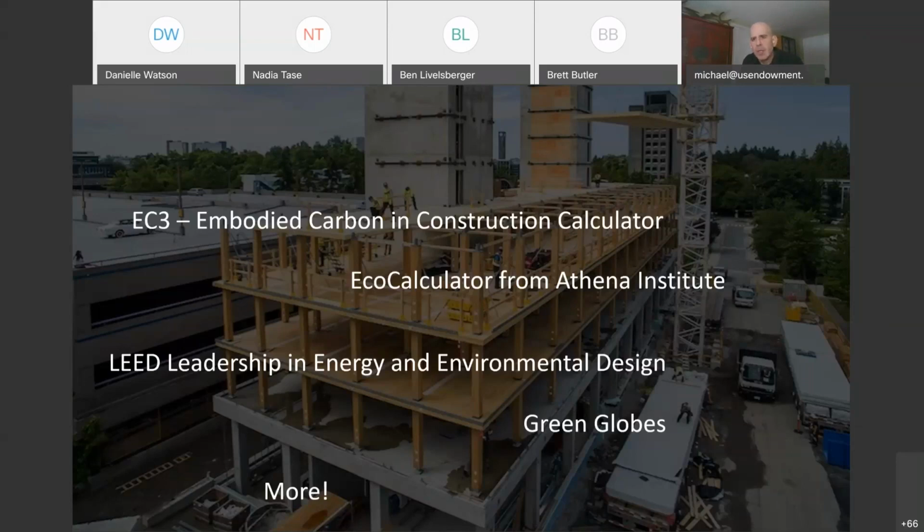It's sort of interesting: if you're looking for an environmental product declaration, an EPD, for concrete, you can go to a ready-mix facility. These are the concrete facilities that you spot all over the country that produce the concrete that goes into those trucks that have the rotating drums on them. They can produce an EPD at most of those facilities for any different type of mix of concrete because they just change a few calculations, they develop an EPD for that, and then they try to give you the environmental footprint of that particular concrete mix that they're giving to you for any particular application. Now, EC3 loves that because they can get very customized looks at what the implications of using a particular type of concrete are in a construction project.